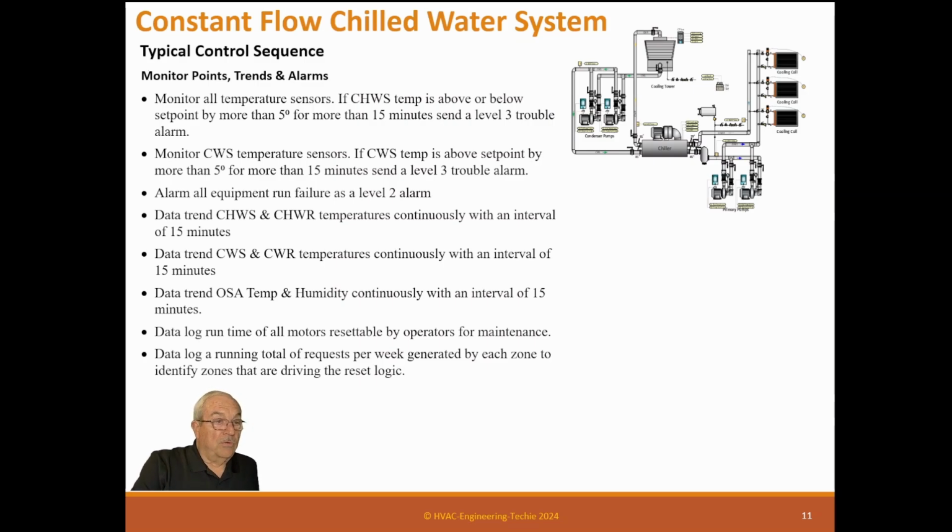It could have a flow problem. It could have a clogged strainer. It could have all kinds of problems. It could have a balance problem. You need to go look and see what's going on with that one. As a general rule, they should all be operating within a mid-range. So many requests go up and down, but if you have 1 or 2 that are crazy, it may be a zone that you don't even want in this.